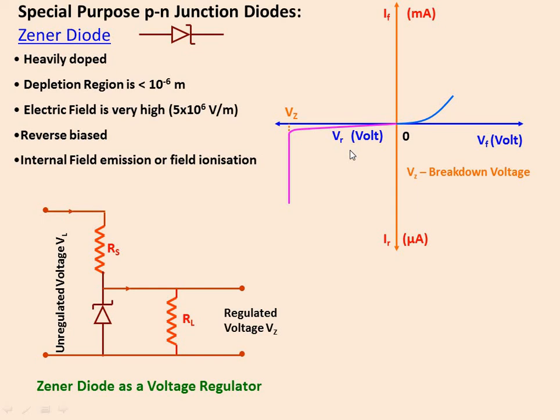Same situation here also. So when a large amount of voltage is applied in a very short range, as it is heavily doped, a very strong electric field will be applied and that disrupts the bonds, and thus there will be a breakdown of that particular diode, and you can notice the sharp increase in the current here itself. In the graph you can notice the second part. The first part is quite similar to the forward bias case of the PN junction diode. Look here, this is the sharp increase. Are we clear with this?